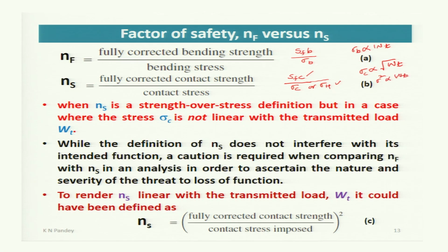Okay. So, while the definition of NS does not interfere with its intended function, caution is required when comparing NF with NS in an analysis in order to ascertain the nature and severity of the threat of loss of function. That means we want to find whether the gear will fail by bending or by surface fatigue.